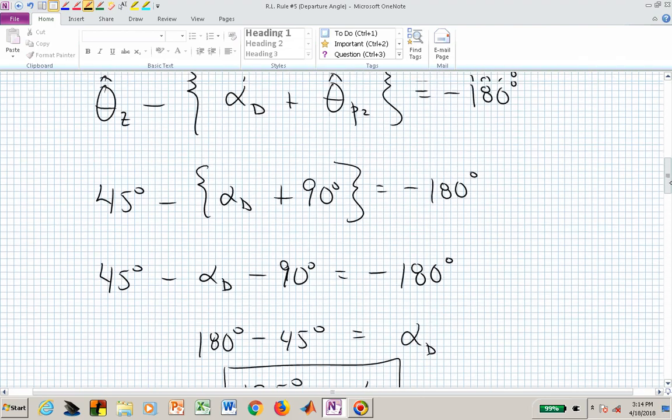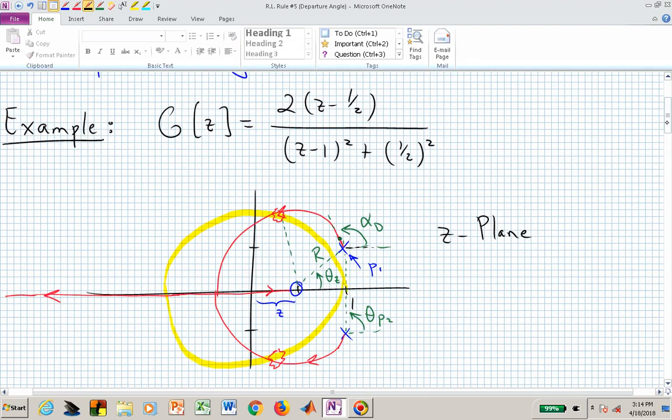And we sketch that root locus here. Now this particular point says the gain k to get us to that point needs to be 0.25. And once we get there, then we're at the lower limit of k for stability.